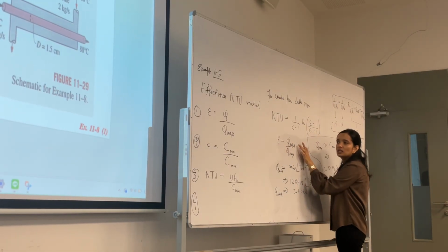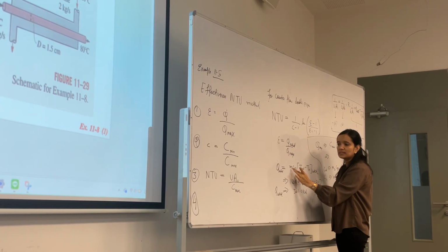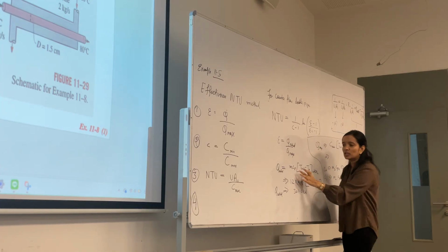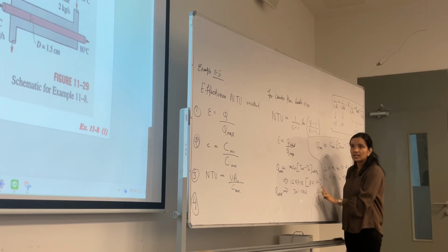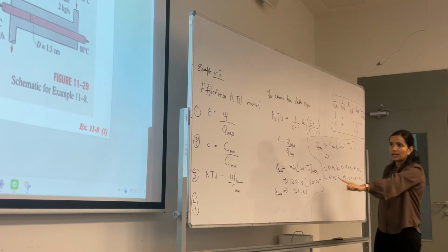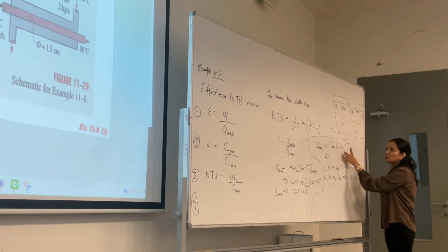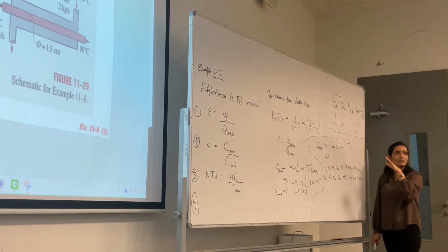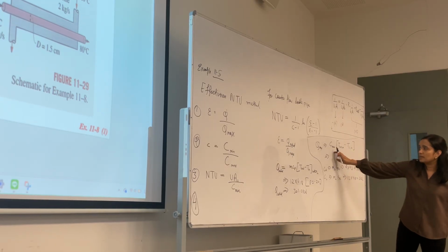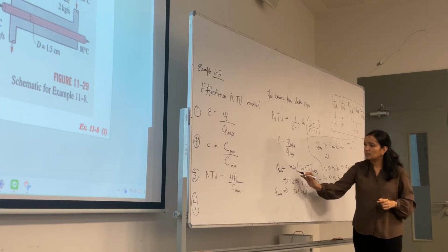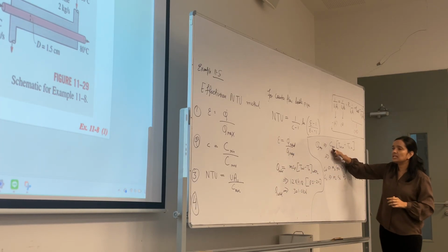Actual heat transfer for water is the mass of the water times the specific heat of the water times the temperature change of only the cold water, outside and inside in the figure, 80 minus 20. Maximum is the maximum temperature difference, so hot in and cold in give the maximum temperature difference, the hot in temperature, and C min. C is the product of mass and specific heat.